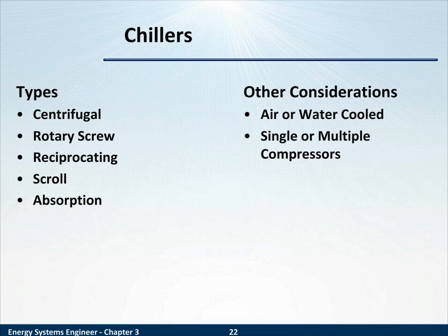Discussing the differences between chiller types, we'll start first with a rule of thumb, a selection based on the stratification created as you consider chillers of different tonnages. We're not going to think about absorption chillers yet, and you'll note for the other four chiller types, the refrigeration cycle is still in play. The refrigeration cycle we looked at before and saw again in heat pumps. What we're looking at here is just the type of compressor. Remember the compressor component of the refrigeration cycle.